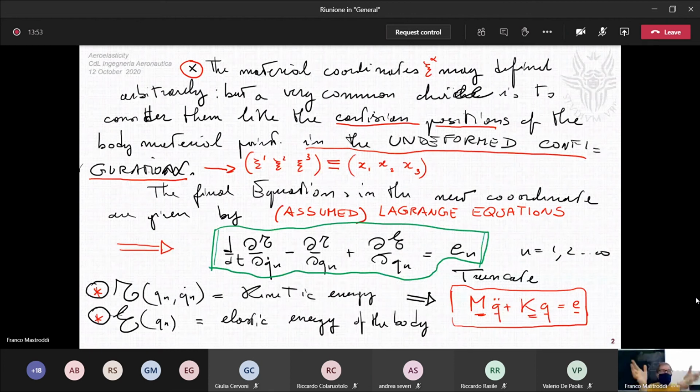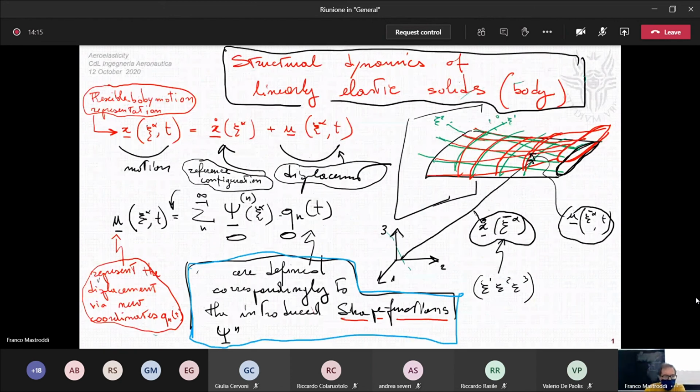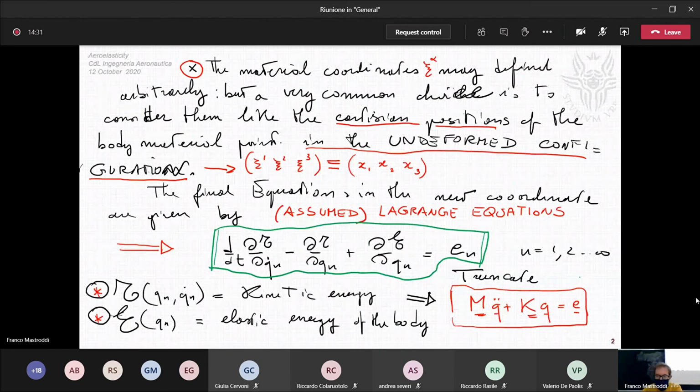By using this set of equations, you have a complicated PDE model for your elastic body, and then you can solve this problem in the so-called weak sense, not strong, weak sense. And by solving this problem in weak sense and assuming this position here, one can obtain the final equation of motion, which is this equation here.